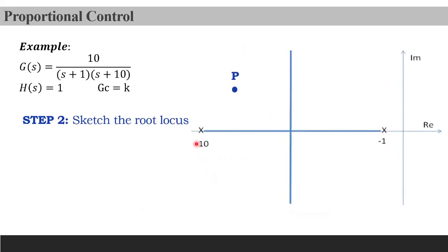All right, so this was your root locus which was given to you, and you can easily figure out how you draw this root locus. And I guess it would be unnecessary to go into the discussion of how you draw it. So if you have any confusion regarding that, feel free to watch the previous lecture, where I used rule number 3 and rule number 4 to sketch this asymptote based root locus in which one angle is pi by 2 and another is minus pi by 2. We have seen a similar example in the last lecture.